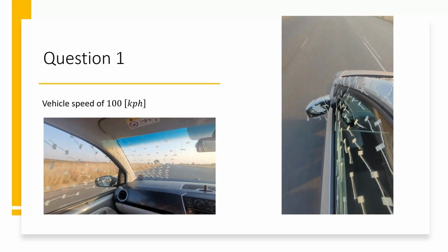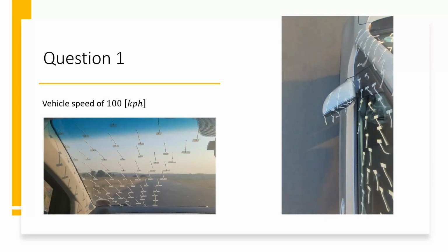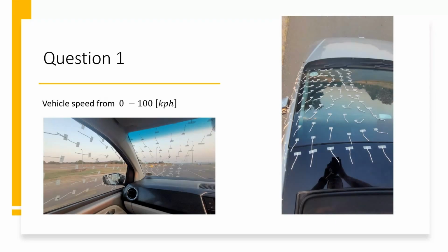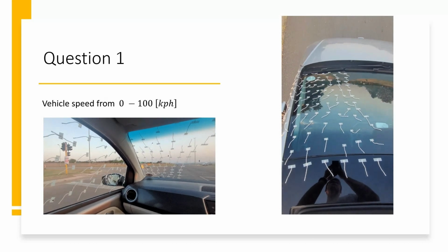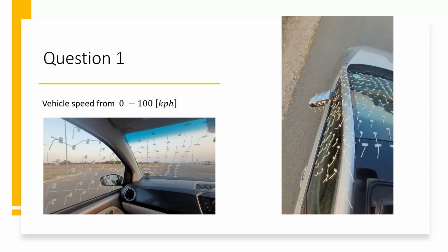This can be seen by the tufts moving in an extremely radical manner, as well as the tufts actually unwinding into individual strands at the tips after driving a while. The flow over the passenger side window follows the direction that the vehicle is traveling in and is relatively attached to the surface of the glass at the bottom of the window.